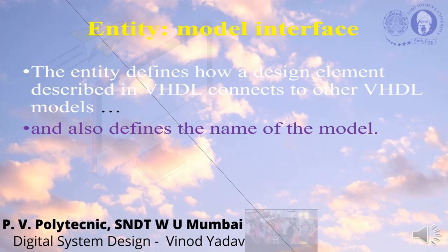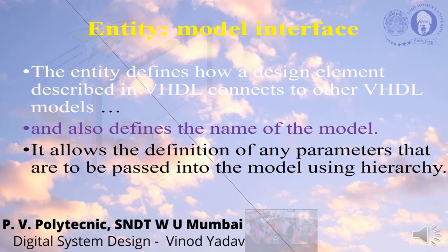It also defines the name of the model. So it is important that whenever you name the file, you should name the file as per your entity name. It allows the definition of any parameters that are to be passed into the model using hierarchy. So you can define parameters in the entity itself, and those parameters could be passed according to the hierarchy.